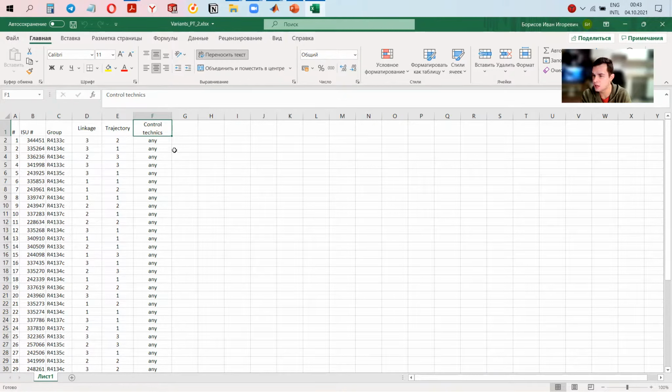For impedance control, you don't need any model. You do this impedance and you just add gravity compensation, but it's going to work even without gravity compensation, though not very well. So you can do any of those that I mentioned, or any other one, just get the trajectory.